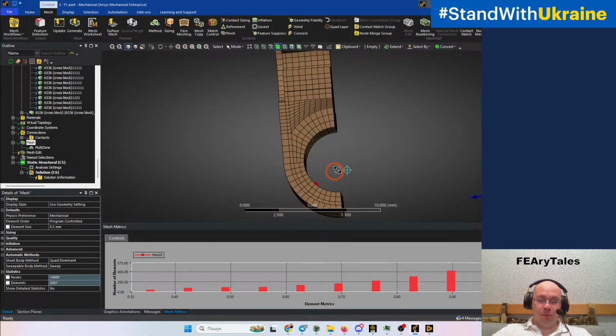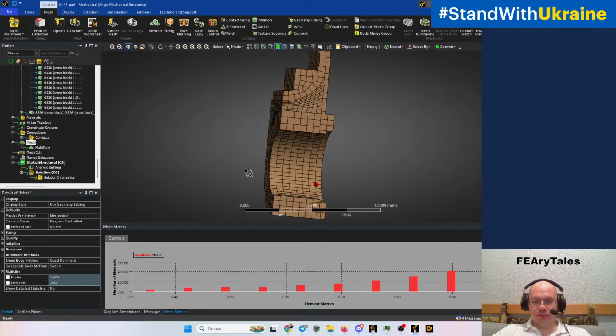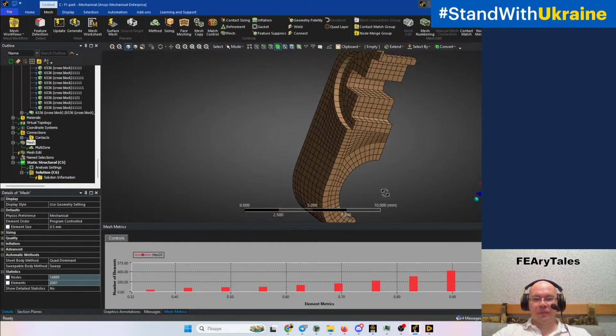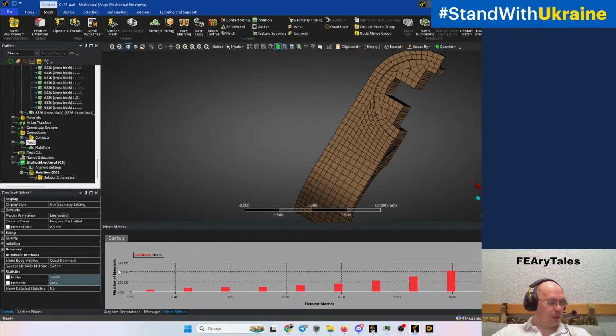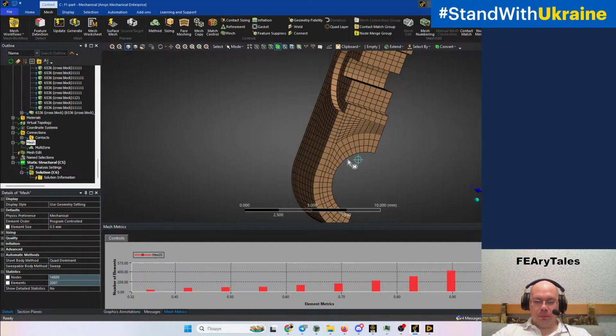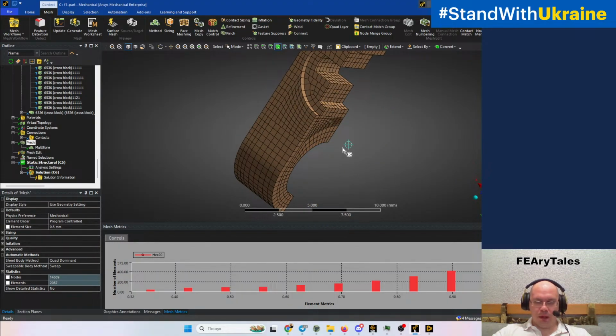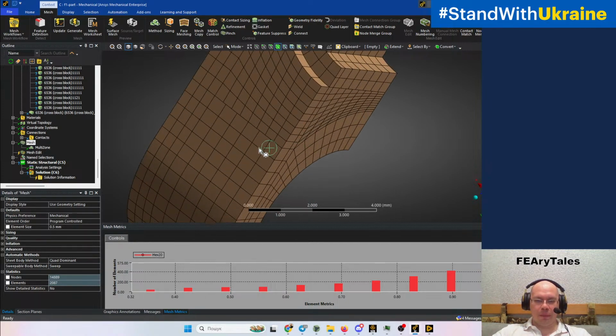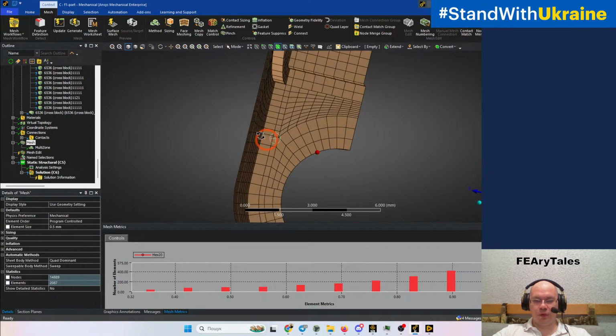But we have good enough mesh. It's all hexa. It's simply all hexa. And if we play some time with the additional preferences, we will create not simply a good mesh, but a mesh which is corresponding one to another with the nodes on the edges and faces, on touching faces.